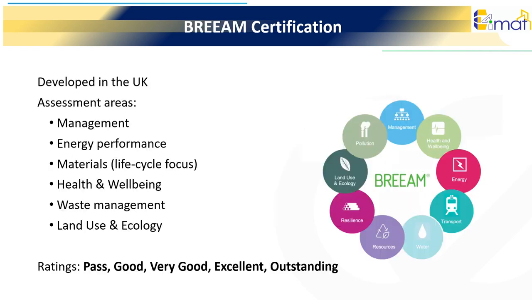BREEAM, Building Research Establishment Environmental Assessment Method, originally developed in the United Kingdom, is one of the longest established sustainability assessment methods. It covers a wide range of categories, from project management and energy performance to materials, waste, health and well-being, and ecological protection. One of BREEAM's strengths is its holistic approach, which encourages teams to consider the building's entire life cycle and its relationship with the surrounding environment. Buildings are rated on a scale from pass to outstanding, depending on their performance.